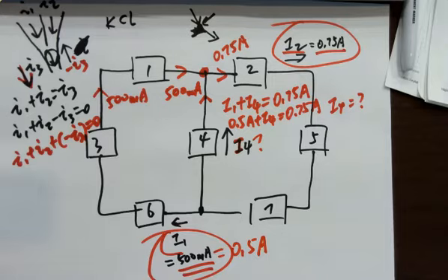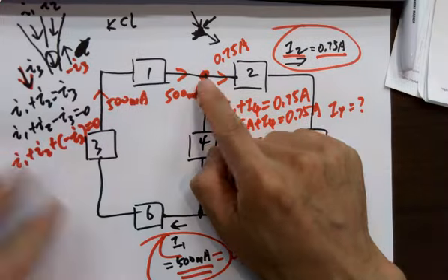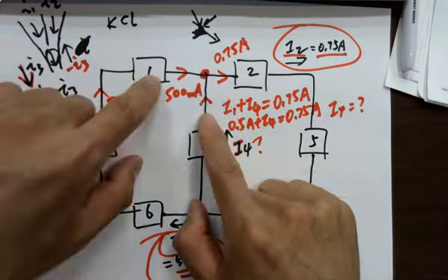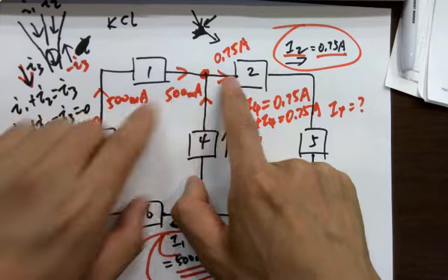Is everyone good on this? Can you explain how you separate the two different nodes? You've got I1 and I4 on that side and I2 on the other side? It's just one node here, right? Just one node, and the currents flowing into it equal the current flowing out.